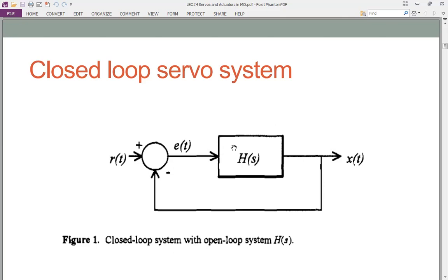This is where we have the split beams, the objective lens, the positionings, and the angles and everything, in such a way that if the output shows that there is an error, that error could be maybe the lens is not positioned properly, then proper action will be taken in terms of actuators. Now, this is where the actuators come in. The actuators will now correct. If it is a wrong positioning of the lens, the actuator will position it properly, and then a new output will be sent.